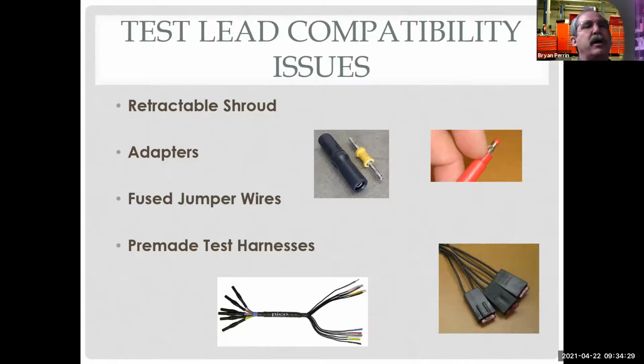So this is a great question. Could I use a tone generator probe, one that phone and IT wiring techs use for tracing and opening? You could certainly use a tone generator, which is basically what the power probe is doing, the little kit that I saw, the expensive one. And then you're using that with the probe. So that's basically the power probe tool that I was talking about. So yeah, that would work. And like I said, the automotive one's about $150. I'm sure there's some other stuff that's less expensive for tracing opens. The advantage of the power probe one is it'll also help you trace the short. So it'll do shorts and opens. But yeah, absolutely. So that's another way of doing it.